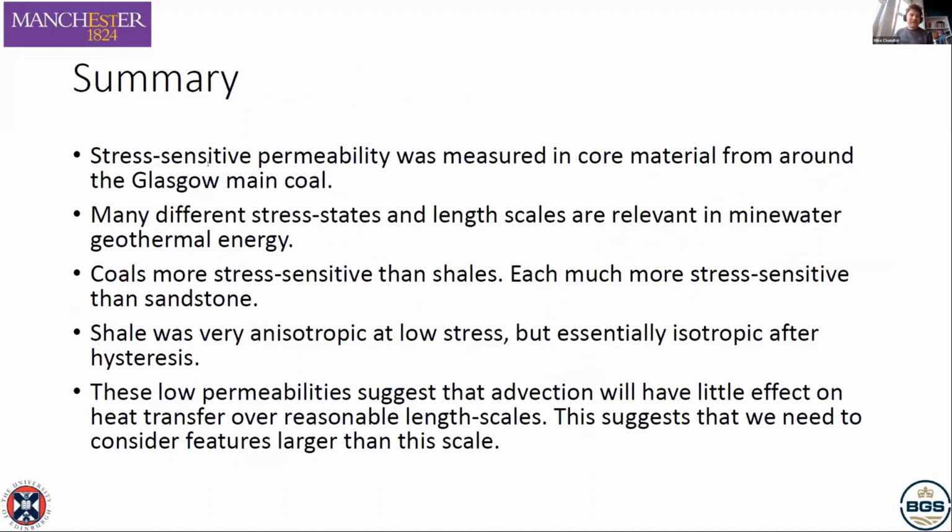So to summarize, stress-sensitive permeability was measured in core materials from around the Glasgow main coal in well GGC01. There's a variety of different stress states and length scales that are relevant in mine water geothermal energy systems. The coals were found to be more stress-sensitive than the shales, and they're each much more sensitive than the sandstones in terms of permeability.